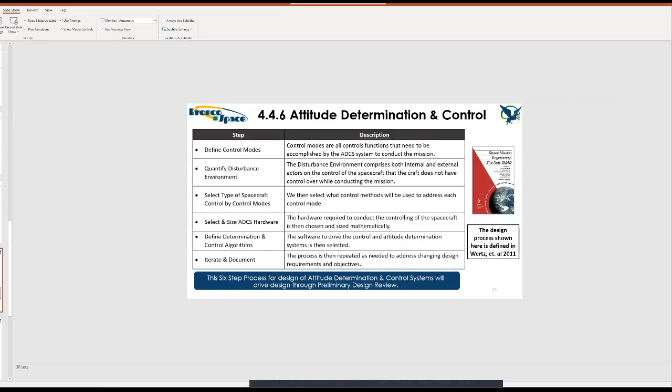Of course, it depends on the size of both. Beefy magnet torquers could theoretically generate more torque and move faster, and at the same time, puny reaction wheels are going to move pretty slow. But yeah, I would say a reaction wheel completing a 180 degree turn in like 30 seconds would be quick work, and sometimes you can move even faster than that.